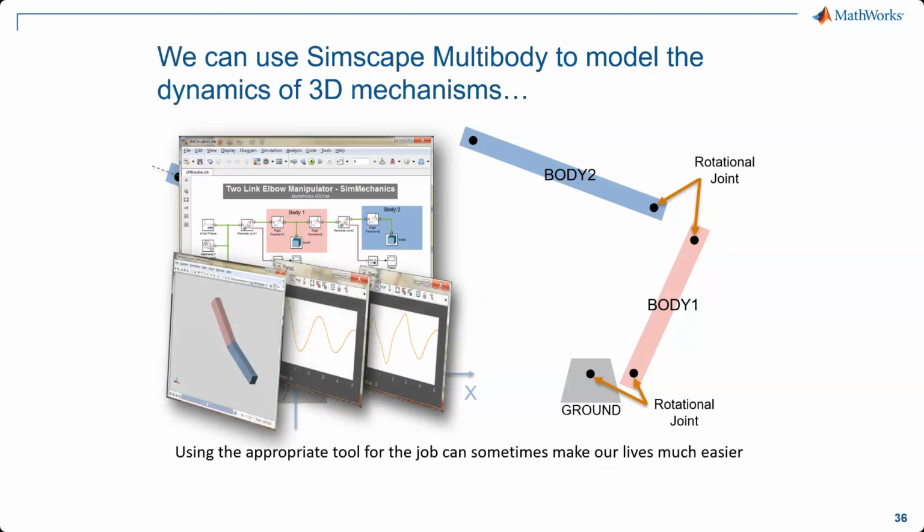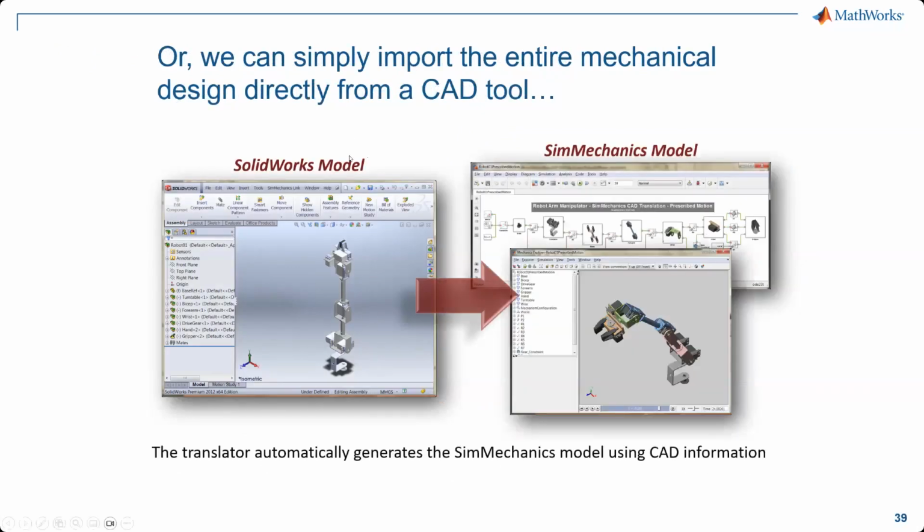And there is one more way of doing it. Suppose I know some 3D modeling software that is very popular, for example, SolidWorks. Here you can see that the same robotic arm is being developed. So you might also be working on various CAD software, which helps you to create this part. You can export this part in an XML format and import it in Simscape Multibody, and directly you can get the same thing here. You can see this logic which is written here in the Simscape model. This is exactly replicating the model that you have created in SolidWorks.